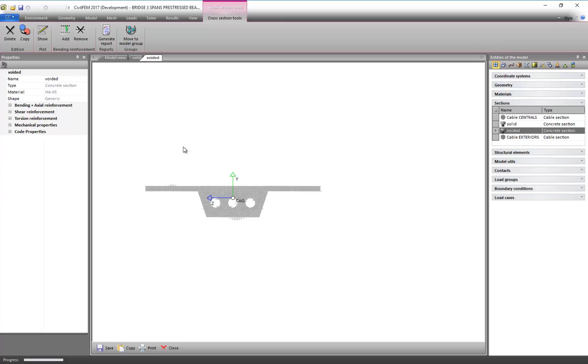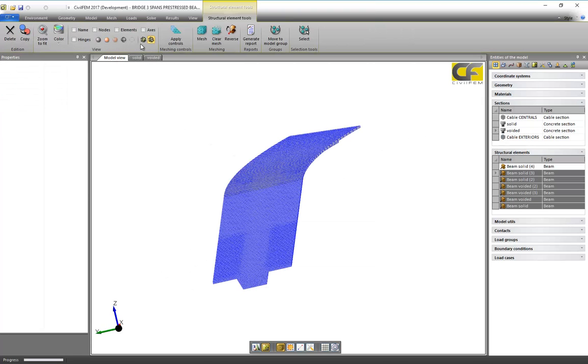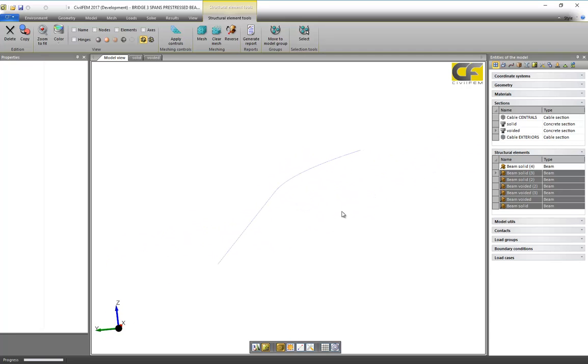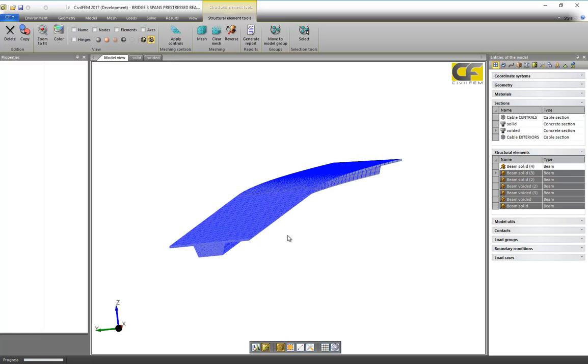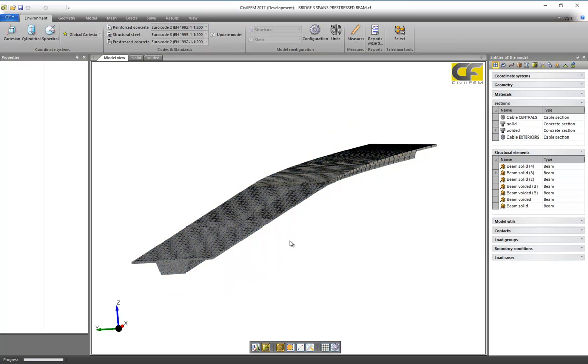In this case, we have defined only the tendons. You can see that these are just beam elements using linear elements. This will take fewer resources, and we use fewer elements, and of course later we can plot the new available results, the isostatic and hyperstatic forces and moments, and plot the interaction diagram of any cross section, any beam element.